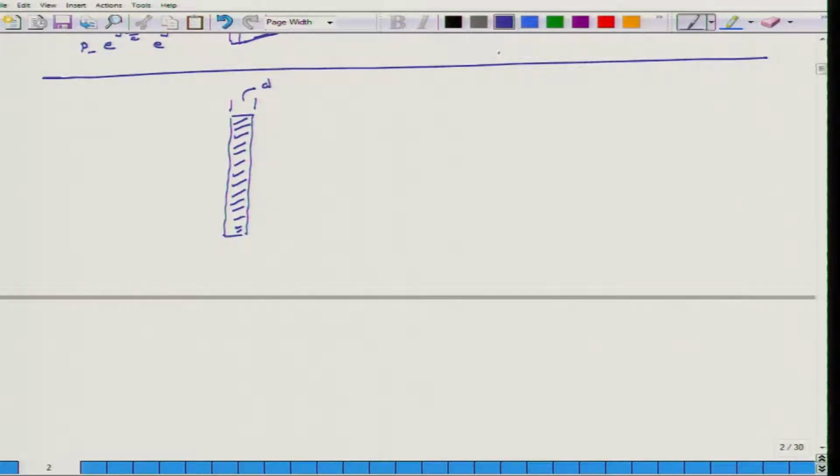and there is a sound source which is generating noise, and because of that noise there is an incident pressure field, and the complex incident pressure field is P plus times e to the minus j omega x over c times e to the j omega t.